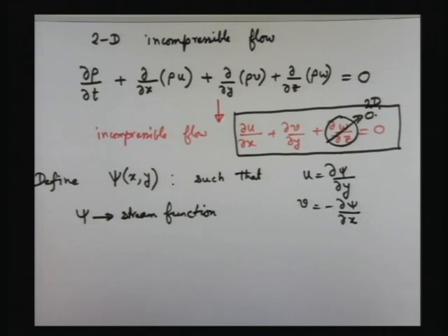So, why are we referring to the continuity equation all the time? Because no matter how complex or how simple your velocity field is or your density field is, it must satisfy the continuity equation. Otherwise, it is not a physically valid velocity field or physically valid density field. So, the stream function, now out of so many names, why is it called stream function?